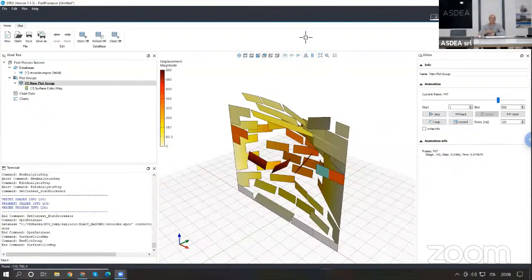Could you provide some information regarding possible explicit solvers? Yes, actually we are evaluating all the possible explicit solvers that are in OpenSees because not all of them are documented. So we are in a process of testing all of them. The first thing that I can say, let me share my screen so you can see the questions of other people. Oh, we are here. The first thing that I can say now is that central difference is the typical one that I would use, is the standard one.